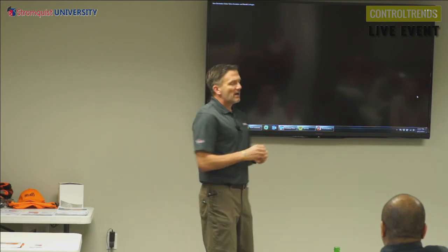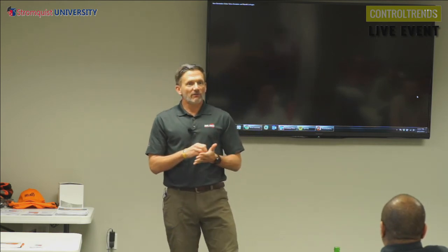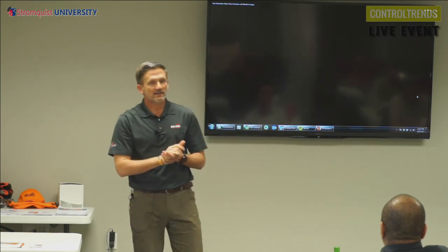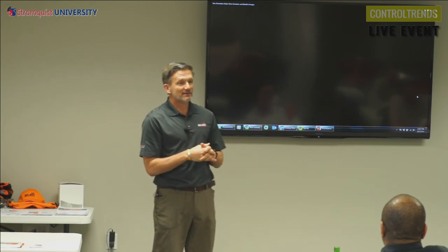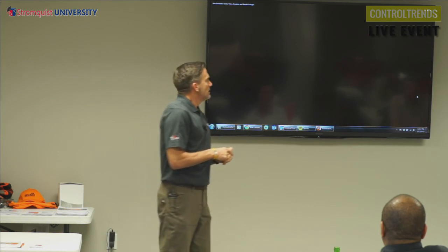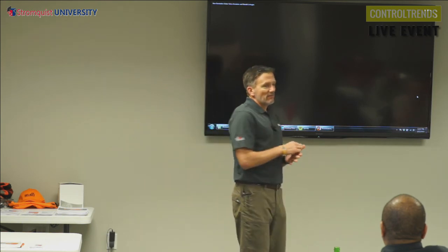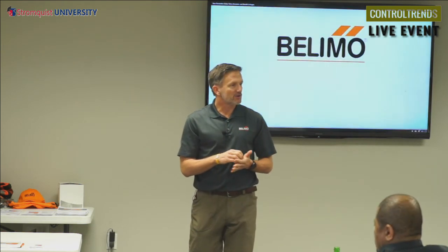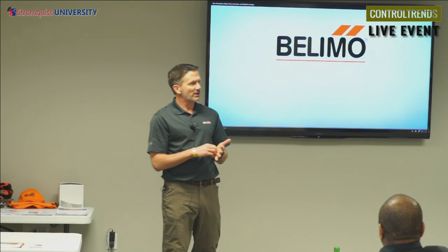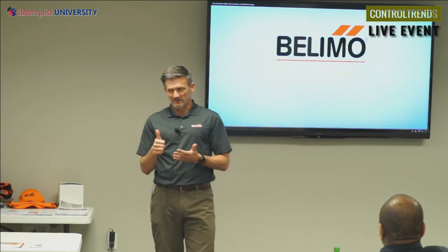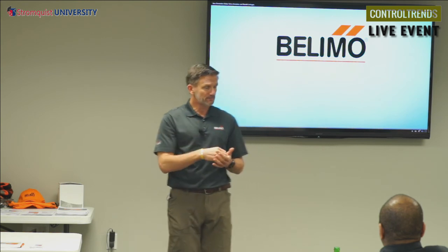The other thing I want to talk about, this is 5 minutes, is globe valve retrofit. Everybody's got globe valves, right? Everybody probably has, or maybe had, depending upon the age of your facility, some pneumatic globe valves still pumping away. In the past, we do a lot of globe valve retrofits because a lot of globe valves, we're going to keep repacking them and keep them in there because you can't take them out, but the valve's still in pretty good shape. We just want to upgrade the actuator because it's either outdated, it's pneumatic, or broken.